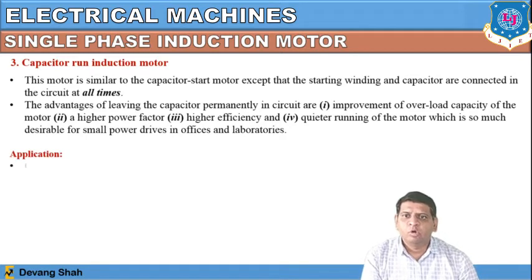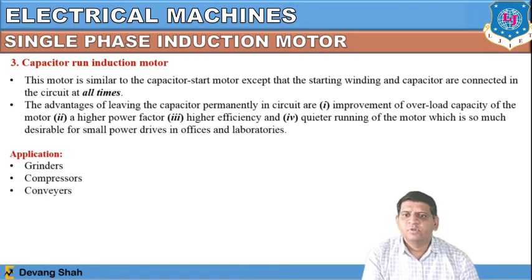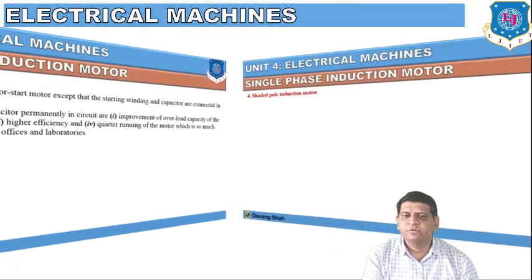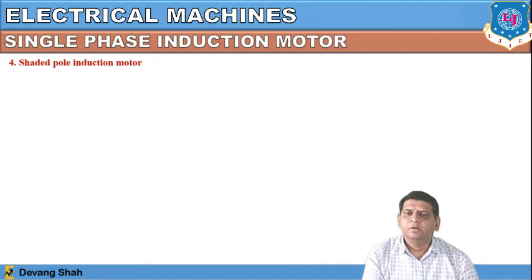So overall, the applications of this single phase induction motor are grinders, compressors, conveyors, fans, air conditioning and refrigerators. You can use all of these with the capacitor start, capacitor run type of induction motor.